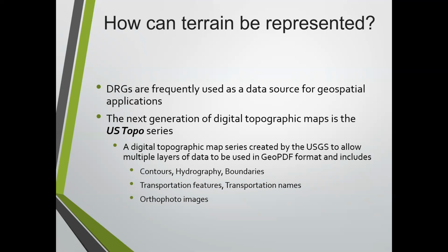And they also include orthophoto images. So remember orthophotos, we talked about those too. Those are photographs where the relief displacement has been brought out of them. Those have been fixed into a pure photograph where the scale is uniform across it so that you can scale things within it. So you can download all of this stuff. I think it's pretty much free from the USGS.